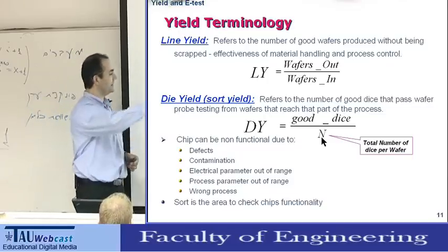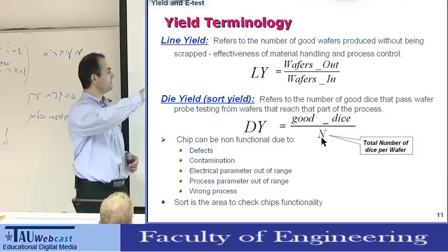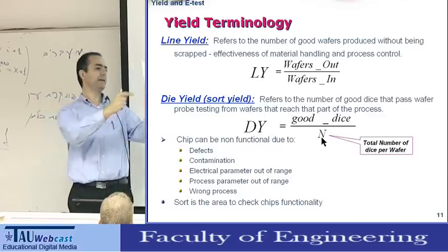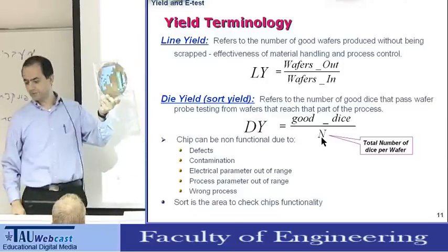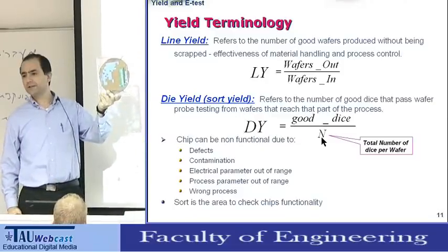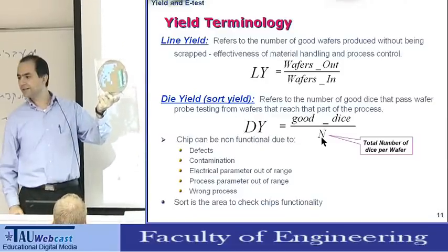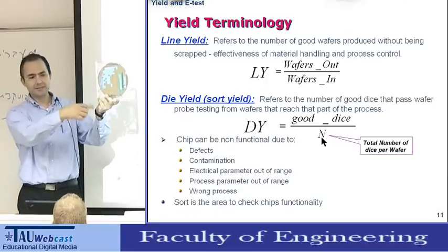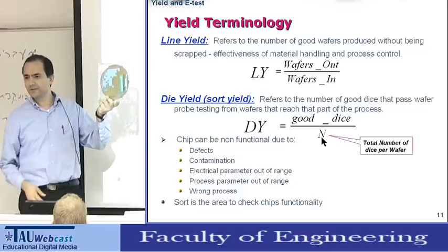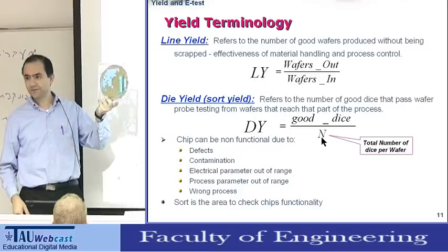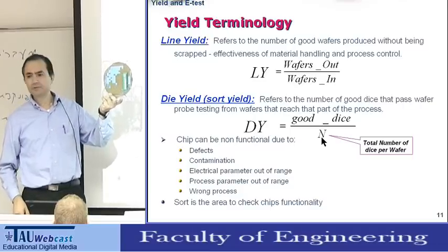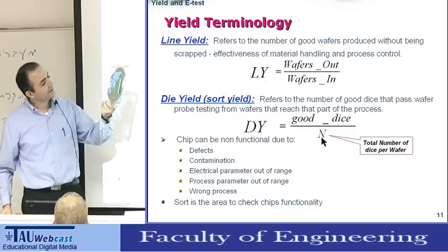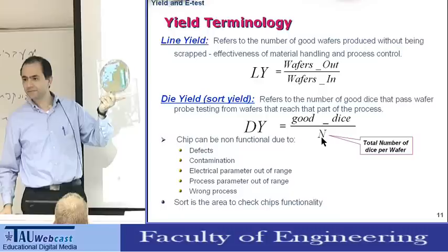And what you can see here on this wafer, you can see that several dies were taken out. These were the dies which were taken out were the good dies. We used them. Actually, some other dies here are good, but this is an example. Okay? This would be considered a very low yielding wafer, right? About 30%. Okay?